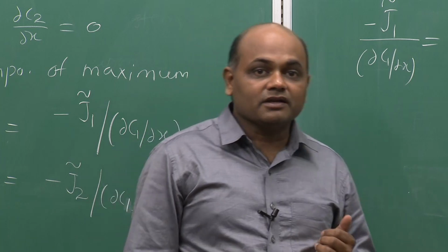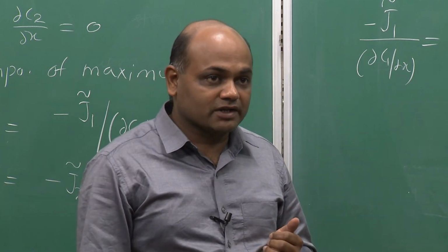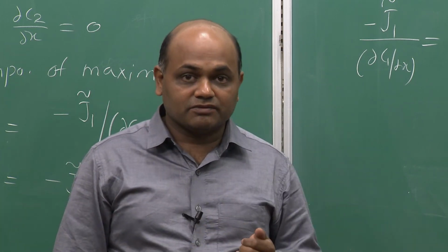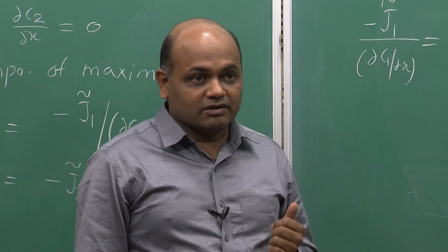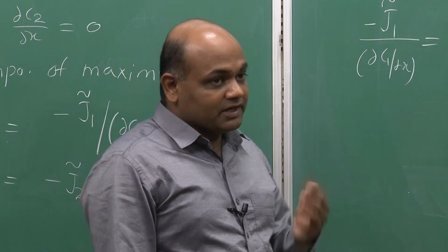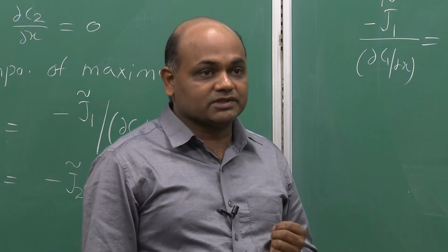Again, it will not be an entire set, because in quaternary, for example, we need 9 interdiffusion coefficients, and so through pseudo ternary couples, if we can form such couples, we will get 4 out of the 9 coefficients.